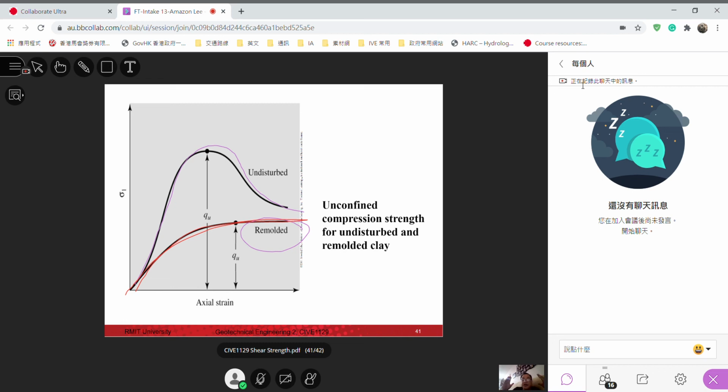Okay, so as a geotechnical engineer, we have to be very careful and inform and supervise our site staff when taking the sample from the ground. Be very, very careful not to disturb, try to reduce the amount of disturbance. And we try to take a sample as close to the in situ condition, the existing condition of the soil in the ground at site, as possible.